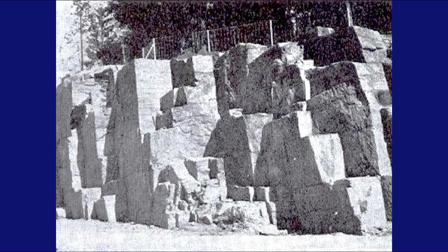And here we have our blocky rock mass. And you can see 3 joint sets. You can see that the edges of those joints are very clearly defined, the edges of the blocks. You can also see that the surfaces of the blocks are pretty straight, so the joints are planar. And we can estimate from there also the joint spacings associated with those blocks based on the assumption of the 2-meter high poles. So if you have a good look at that rock mass to get a picture in your mind of that, and then I'll go through the calculation of a typical value of the rock quality designation RQD.